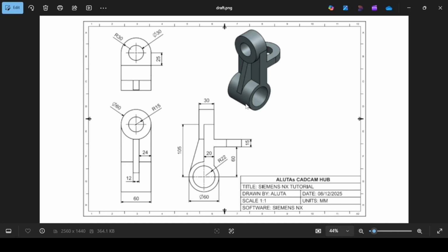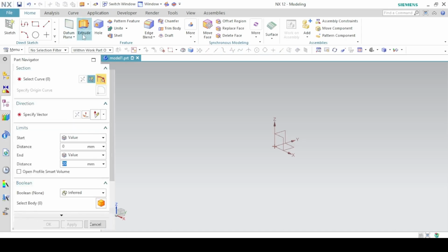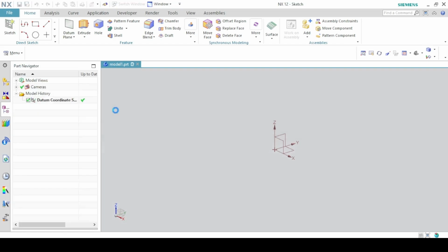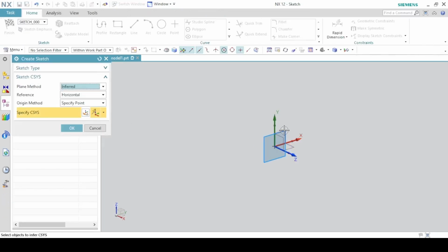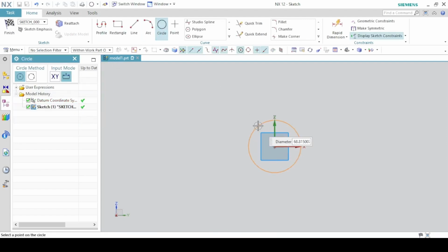The first thing we are going to do is the bottom cylinder here. We're going to use dimensions on the side view. The outer diameter is 60 millimeters, and the height of the cylinder is 60 millimeters also. So that's what we are going to do. With the extrude feature, because we are adding material, sketch section to sketch the profile of the circle, you're going to use the YZ plane, which is also the side view or the side plane. Okay. Draw a circle of diameter 60. Finish.